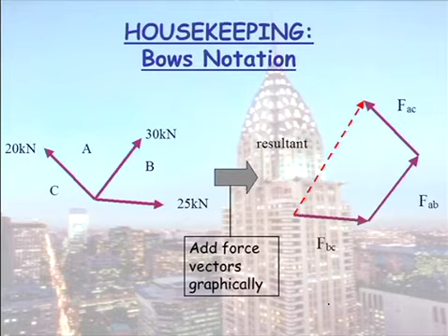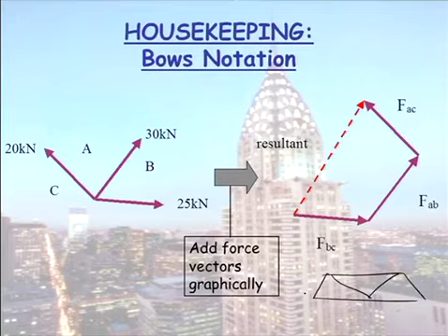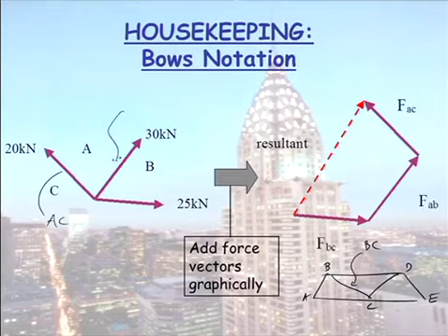And when I say moving on, just one more thing we need to look at. The problem set questions sometimes have a funny numbering on them. When we have a truss, generally nowadays, you would designate each joint a name. And then you would call this member here member BC because it runs between joint B and C. However, another way of naming members is by looking at the letters either side of where the member runs through. So this member here would be member AC and this member here AB.